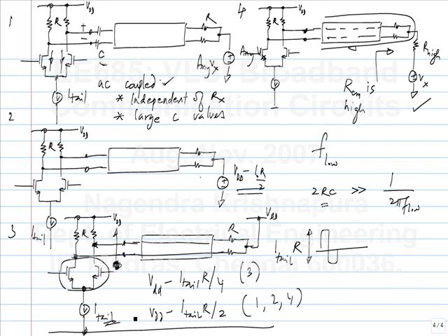Then you go to topology number 3, and it will definitely be well in the saturation region. Then you can further increase the I_tail and increase the swing if you want to. All of them are driving the same swing, and this has the highest common mode voltage. Alternatively, if you adjust all of them to the same common mode voltage, you can have a much larger I_tail here. Okay, think about what else might